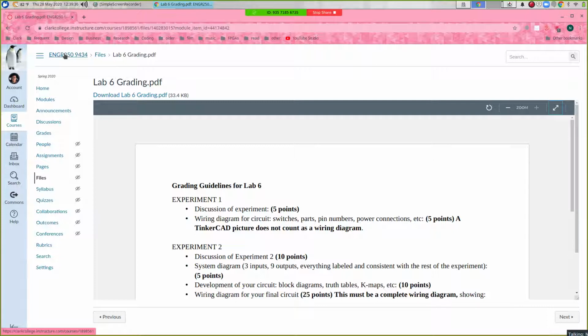Okay, the clock is going to drive the timing of the yellow light. It's going to drive your delay circuit, basically. But ultimately, you're going to have 3 switches to simulate the 3 cars, and you're going to have 9 lights, red, green, yellow, times 3.